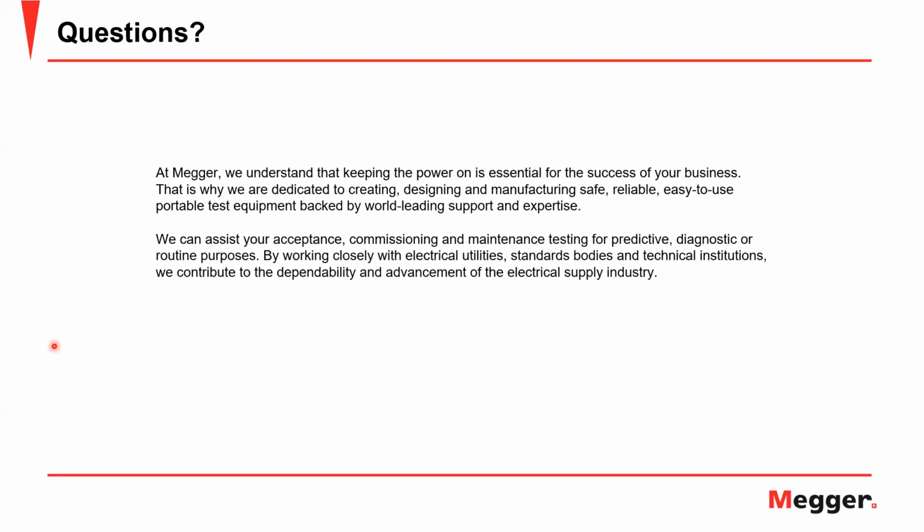Whereas in the fuse saving scheme, it will be good because it will also increase the reliability in indices like SAIDI and SAIFI, but it will decrease the momentary indexes, because there would be a lot of momentary issues that would happen. So it completely depends on what kind of system the customer has.